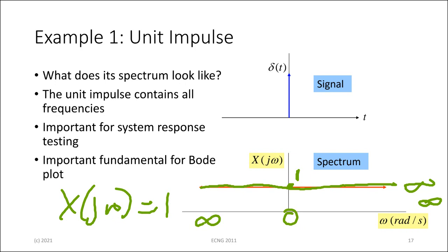By doing an impulse test on a system, you are able to subject the system to an incredibly high frequency input. That is why it's such a critical test, and why we do it even when you get the transfer function. The transfer function now tells you what sort of frequencies the system is going to respond to in response to an impulse being put in. Fair enough? Right?